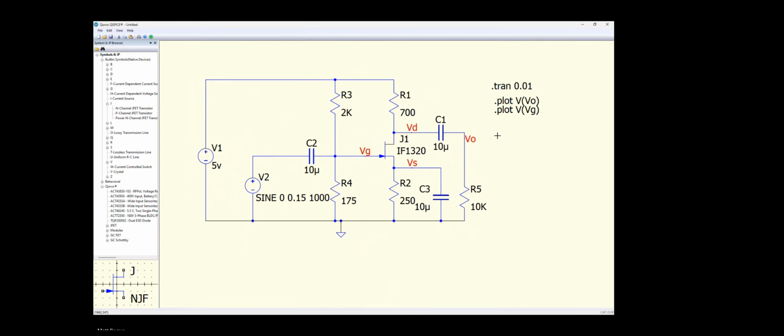We can also have the simulator measure some signals for us. We will break these into two categories. The first is static conditions and the second is dynamic conditions. We will create a dot command that we will then turn into a comment. Hit the period key to signify a simulator command, but do not hit enter, just type the words static conditions. Hit enter. This is an invalid command, so if we tried to simulate, it would produce an error.